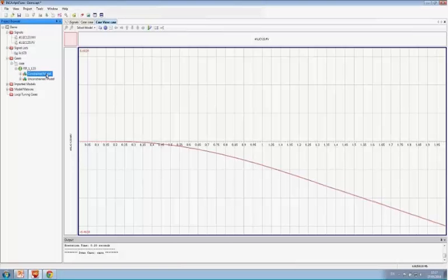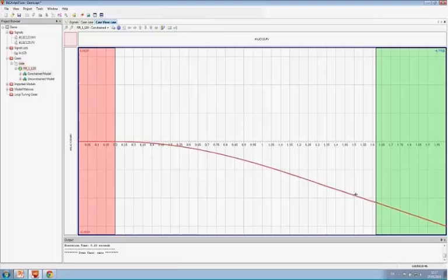So let's say if I wanted to fix the dead time here, I can select the constrained model and fix my dead time here, and as well I can fix steady state behavior on this side. So now I am enforcing some dead time, and I'm enforcing the time to steady state.